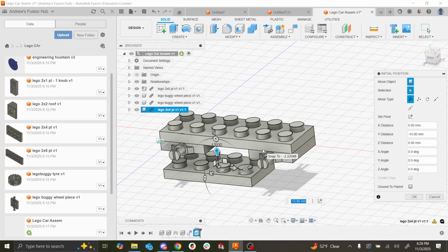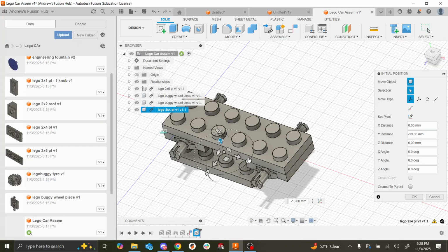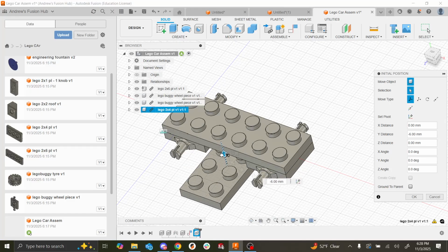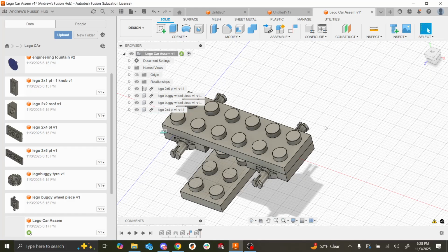There's a slight tolerance in between all the parts. So if you have the two faces up against each other, you're going to encounter a small gap, right? But in this case, the gap is intentional. But I think using the constraint tool is going to be a little bit easier for this part versus joints.